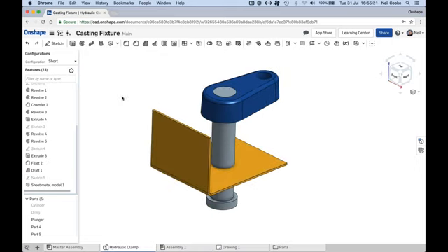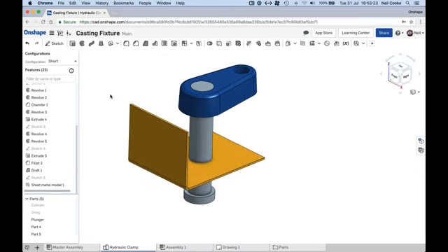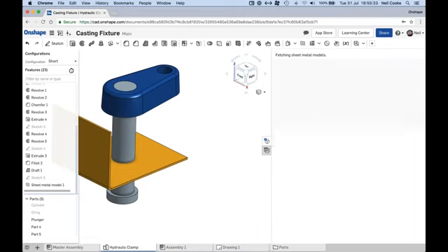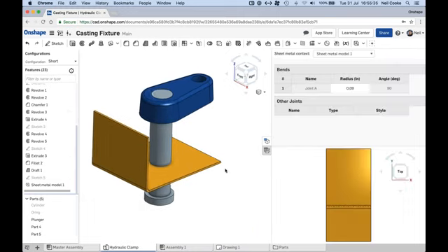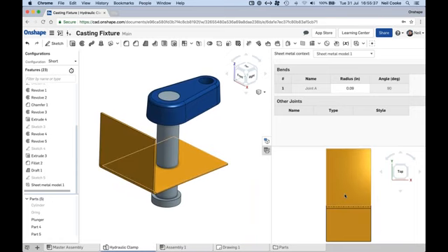The difference here, and really, there's a full webinar's worth of content for sheet metal, is that once you create a sheet metal part, and you can create as many as you want in the same part studio, an extra tab appears here, which basically gives you the flat view of the model. So you don't have to flatten it to see if it's a viable sheet metal model. You can see it directly here. You can modify the radius from the table view here.